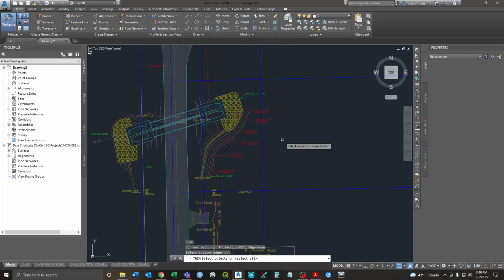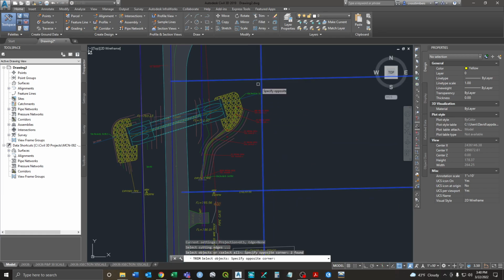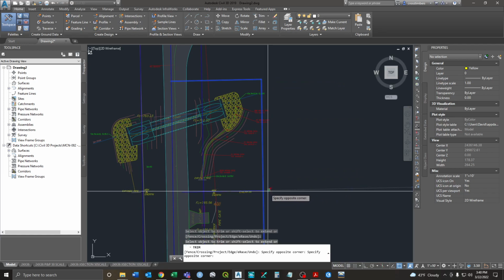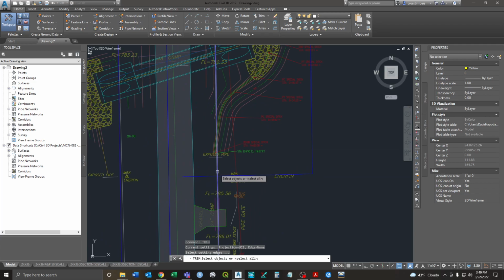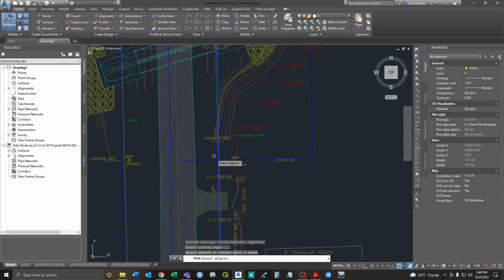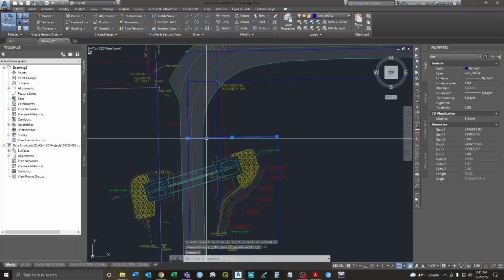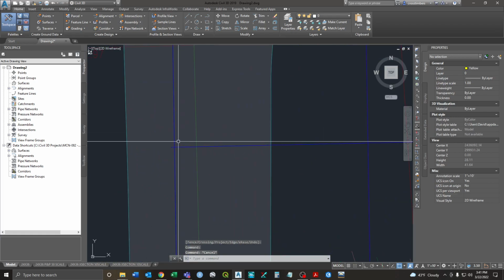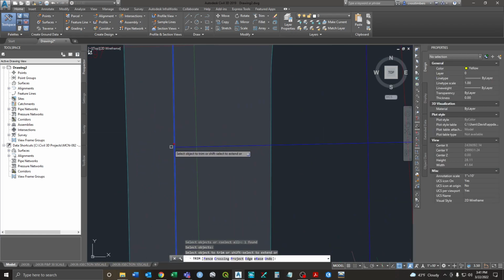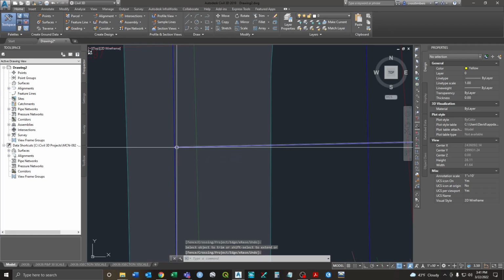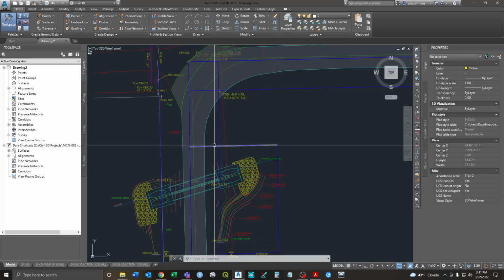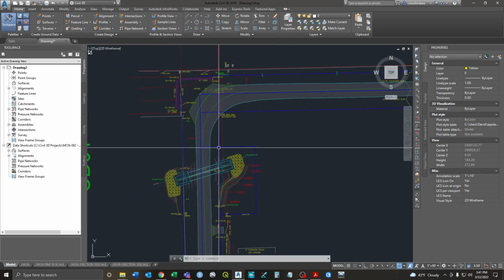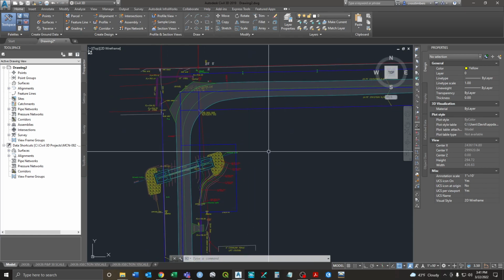And then again, it's the same process. We'll just trim it up. We'll just start with these outside corners because we know we want to lose them all. Now, again, this far corner, because it's the furthest away, we're going to trim to the statutory right-of-way line. But the inside corner, we want to trim to the section line. I did leave myself a lot of room there, but okay, so that way it's buttoned up to the section line, because again, we're going to go from here to the point of beginning. Okay? And so now we've got our right-of-way here.